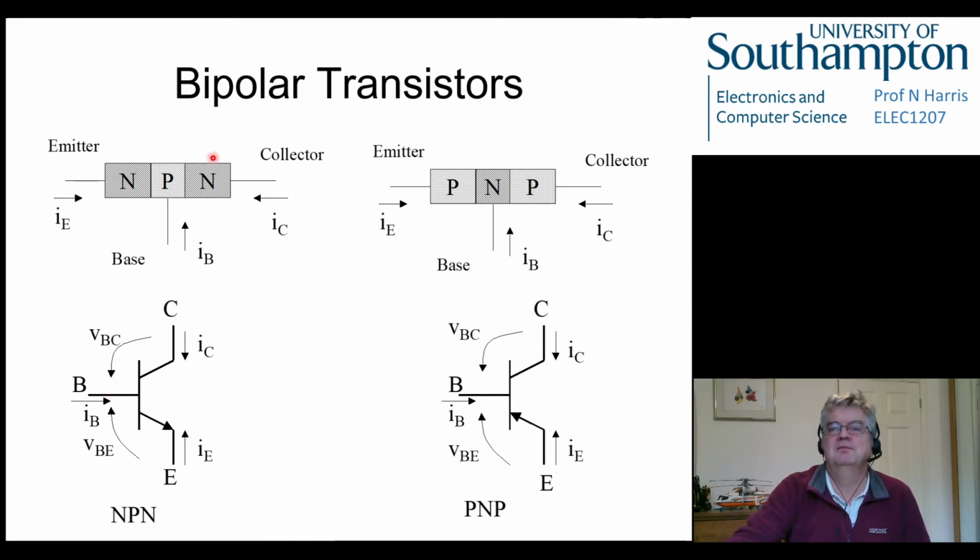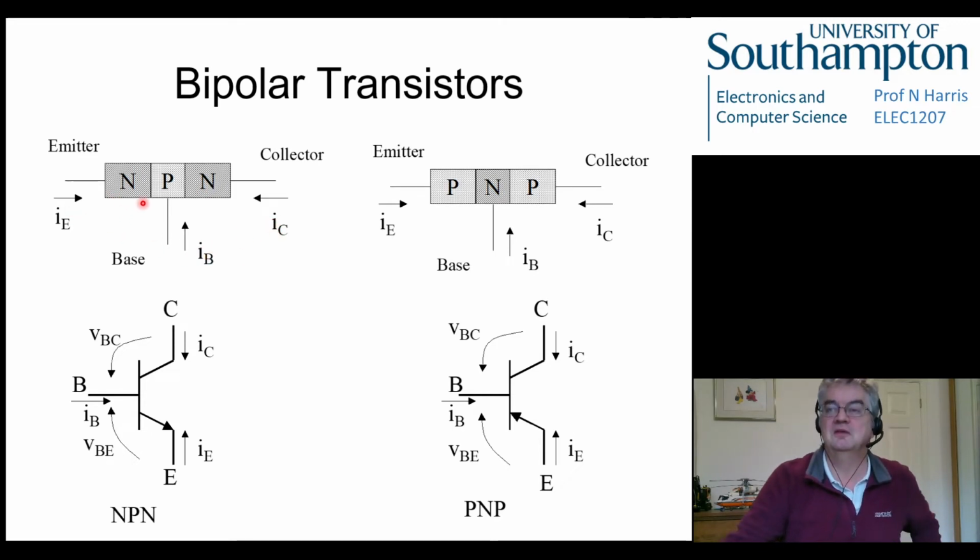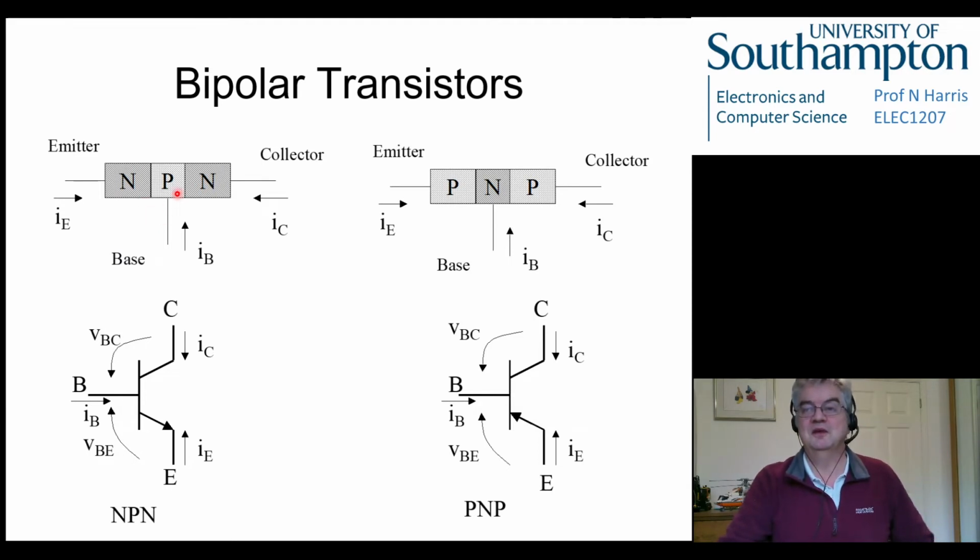So again, it's looking a bit like a node, so we'll have some definitions, and we define currents going into these nodes. So we've got collector current, base current, and emitter current, and they're defined as going in. Obviously, they can't all be physically going in, so at least one of these is going to be a negative current. And then the PNP is just made slightly differently with different materials, and we end up with a symbol that's slightly different. On the NPN, the only difference is an arrow coming out in the emitter, and on the PNP, we've got an arrow going in on the emitter.